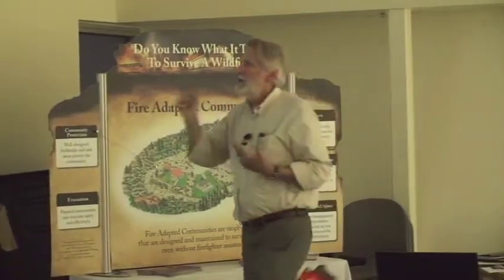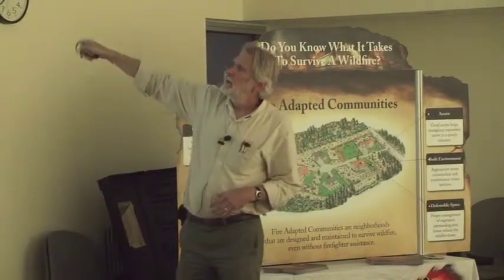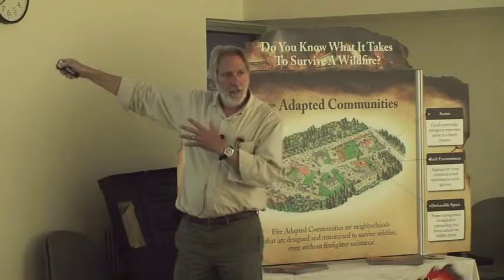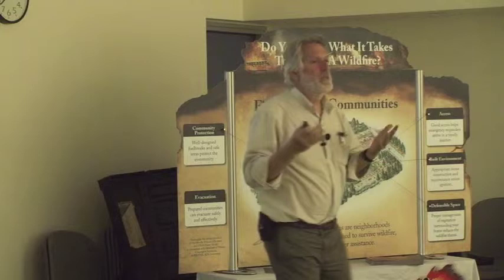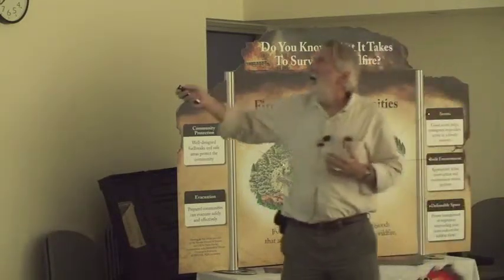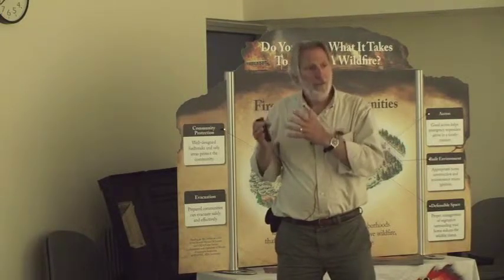So the things that we need to worry about then with regard to decks and other parts of your house that we talked about in terms of this exposure business is the likelihood of fire getting there to have an underdeck exposure, and then embers landing on top of the deck, and what might be on the deck to ignite. And then also there's the combustibility of the decking product itself.